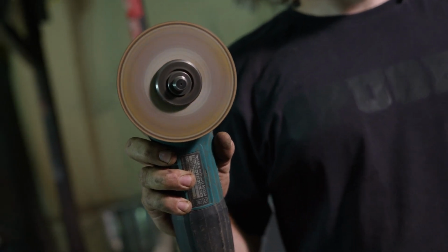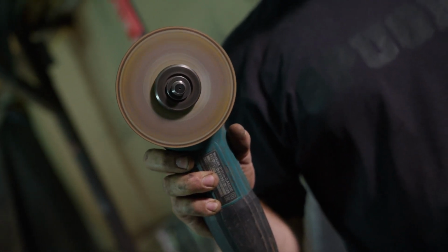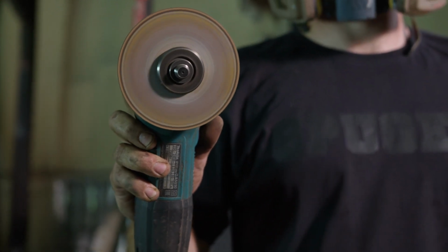Finishing specialist. When working with ceramics, don't forget to specify the color and tone of the grout between the tiles. Other professionals, depending on the type of renovation you're doing, you might also need a carpenter, a lighting specialist electrician, or a shower screen installer. So make a list of these people and the items you'll need to stay on top of things. Additionally, you should specify the alignments of the ceramic pieces before they start working, especially if the tiles are not square, or if the bathroom doesn't have parallel angles.